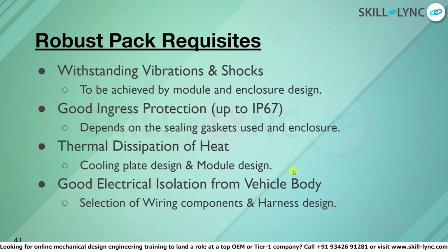So this means that all the enclosures, modules which are designed, and all the mounting of the BMS inside the battery pack would be subjected to constant vibration, when it's on the road, on the train, being shipped, or on a moving vehicle which is discharging. Any loose contact, like loose screws, could make the whole pack stop. The BMS might terminate the whole pack because of any loose contacts or loose wires. So it is very important that when the whole pack is assembled, the right torque values are used.